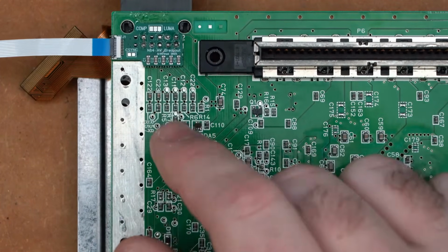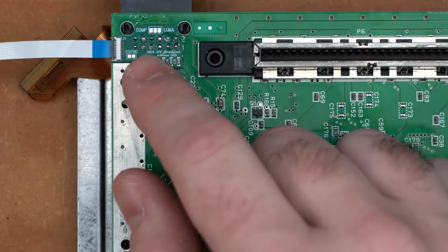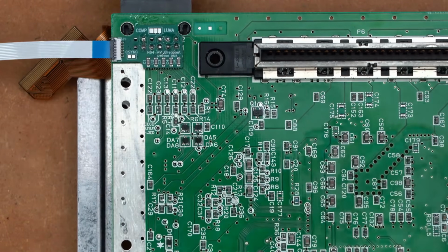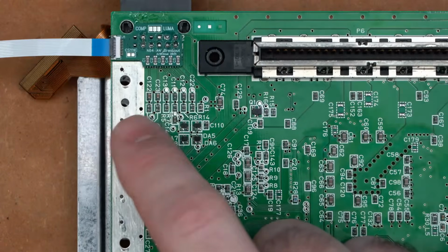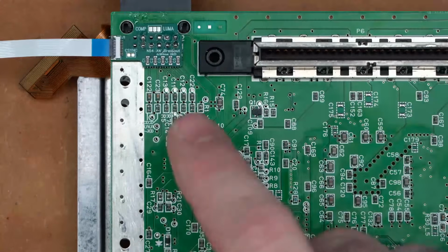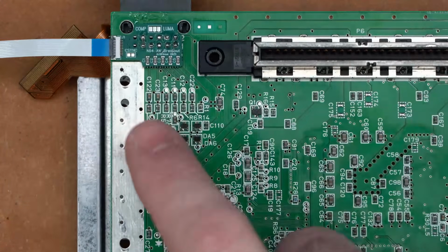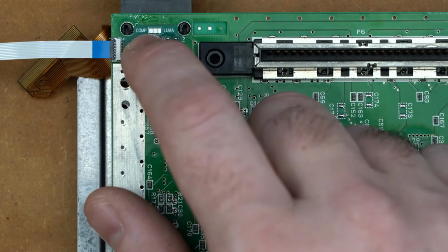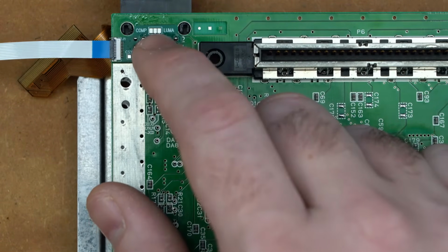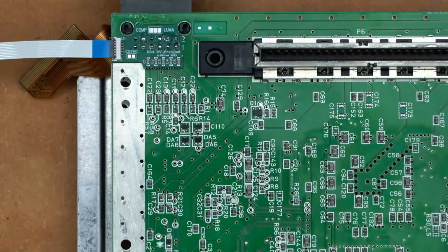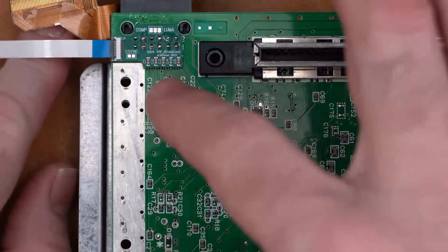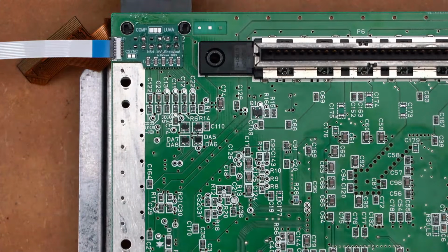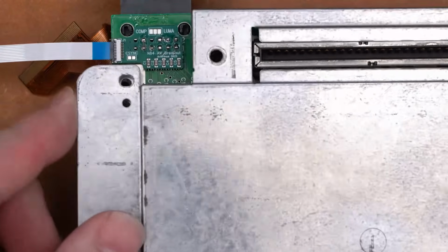Basically, if you want to send the C-Sync signal down the composite pin or down the Luma pin instead of sending composite or Luma, you just remove the components for whichever signal you want to disable and convert into C-Sync, and then you close either the comp side of this jumper or the Luma side of this jumper. That's really all there is to it. So in our case here, we're not going to close any jumpers. We're just going to flip everything back over and start putting it back together.